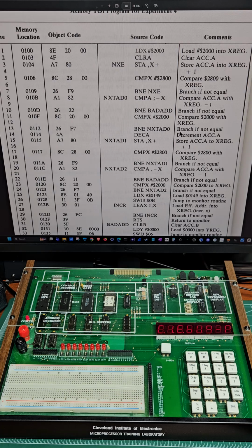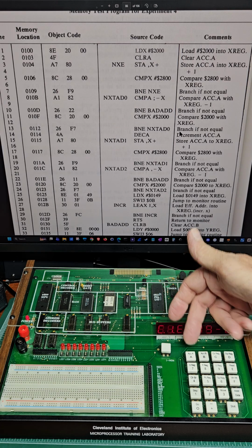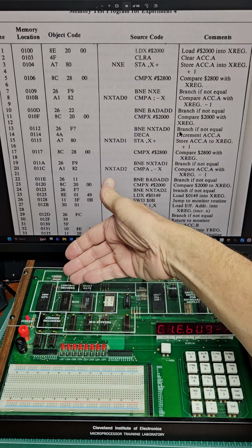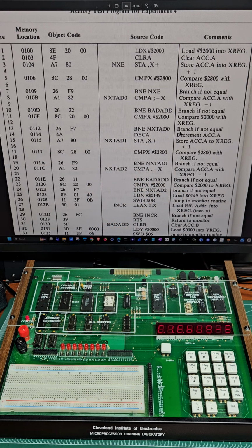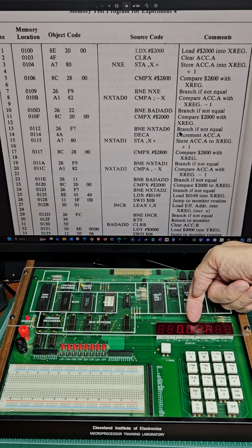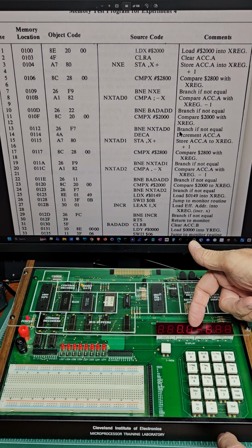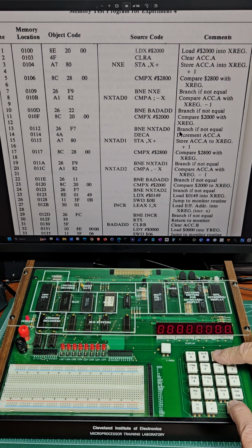Now to access the CPU, you have to do it through the keyboard. Some of the things that you can do on the keyboard: it's got a button here, accumulator A. You can actually look and see what's on the A accumulator on the processor itself. We press this and the A button, and it shows right now in accumulator A, it's got 00 as the data inside the accumulator A. And also you can look at accumulator B, which is also 00. See, there's not a whole lot going on there now.